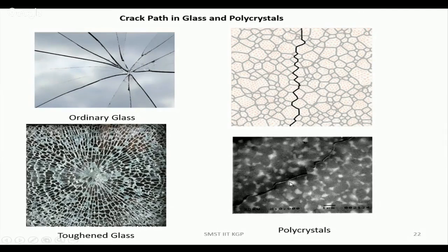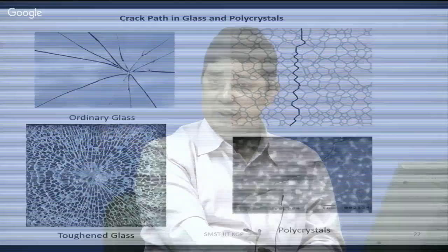the bright one is zirconia and the black one is alumina. Here you can directly see there is a toughening mechanism, and that is why the crack doesn't follow a straight line, it follows zigzag. So now our job is to design the material or other biomaterials in a way that under cyclic loading and unloading conditions, the crack does not have catastrophic failure.